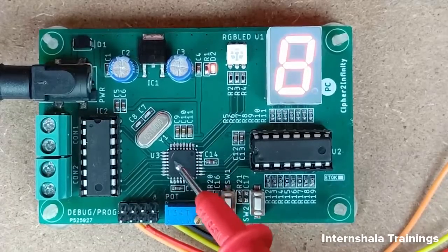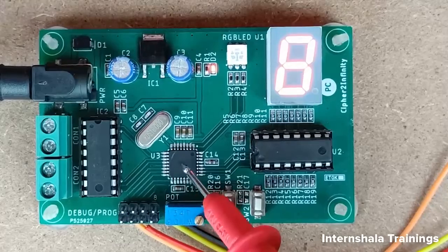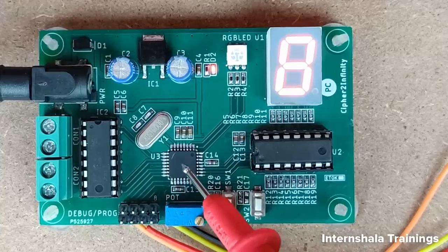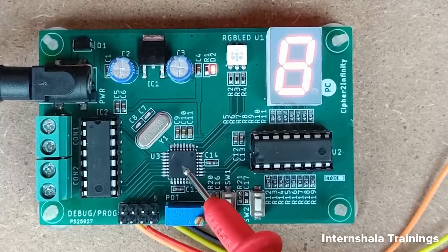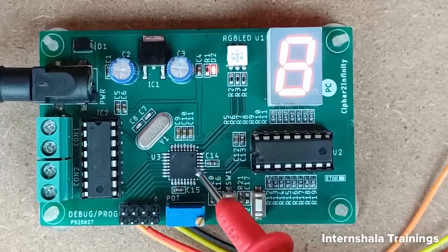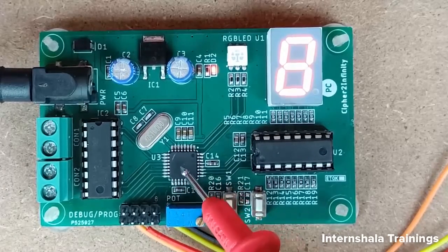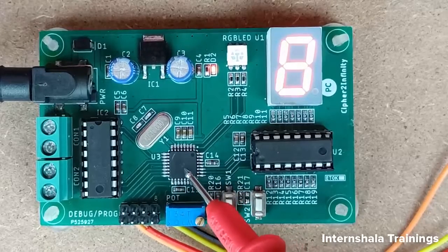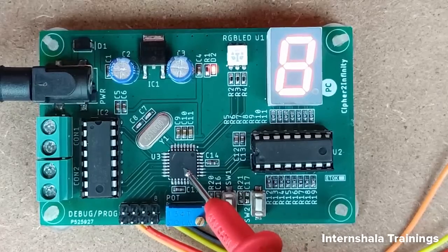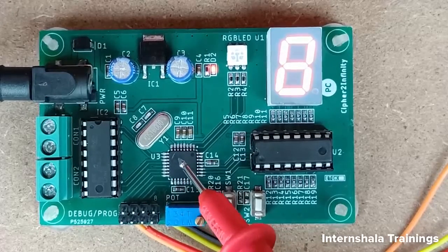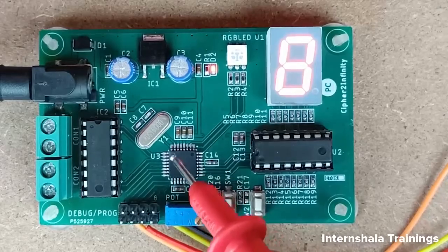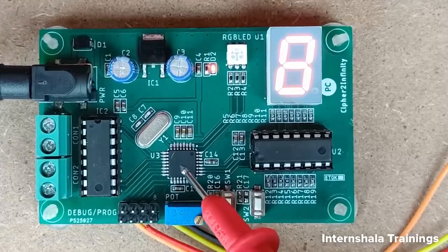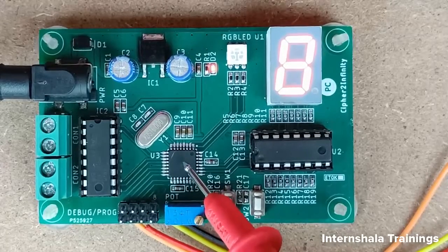Then the second mistake that you should avoid is, even after soldering the controller on the PCB, it might happen that the controller will not work properly. This actually happens because of dry soldering of the pins which are connected to the PCB. In that case, what you can do is touch-ups on all the pins, and that will resolve the issue related to dry solder. You just have to make sure that you do the touch-ups all around, on all the pins of the IC, and that will resolve the dry solder related issue. So that's basically the second point.